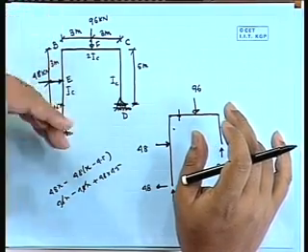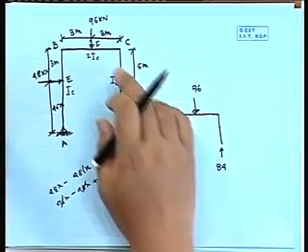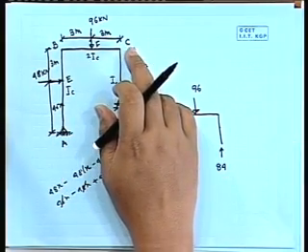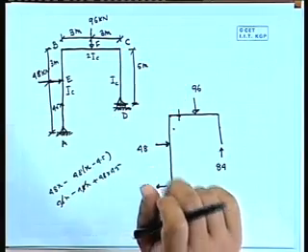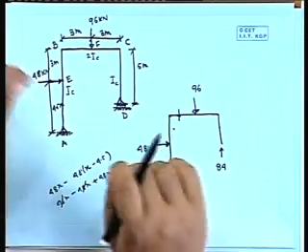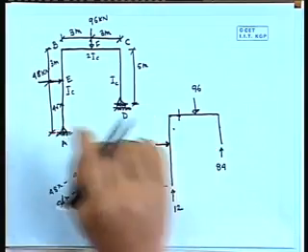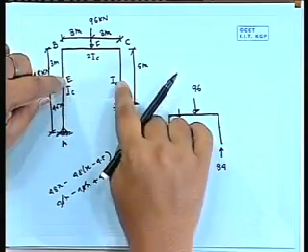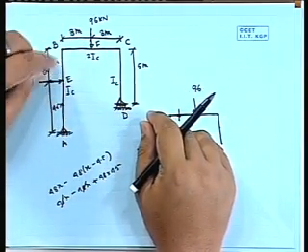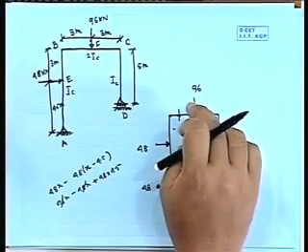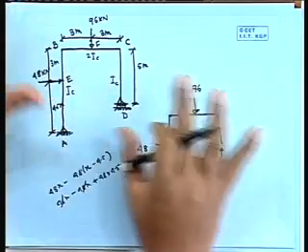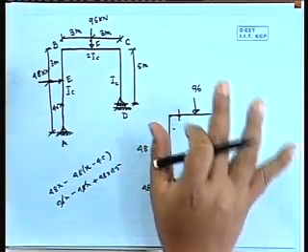When it is a vertical member, definitely it will not come down. So here also C can't undergo vertical movement, due to the member CD, where the axial deformation we are not going to consider at this level. So it can only move in a horizontal direction, because these members can bend, and due to the bending it may shift from its position, or automatically the whole thing can go to the right side or left side, right. And D can definitely move in a horizontal direction, plus rotation.